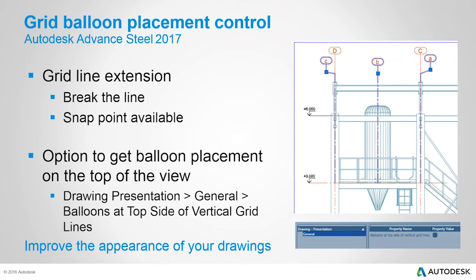Something else you might notice in that picture is that it's an elevation view, and I've got grid balloons at the top of the view. There's a new option been added into the system for that, and like all the options, it's under defaults in Management Tools. So if you find Drawing Presentation, General, and then balloons at top side of vertical grid lines, as shown in the bottom image there.